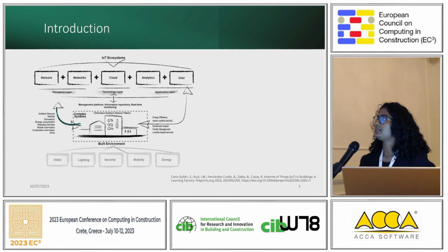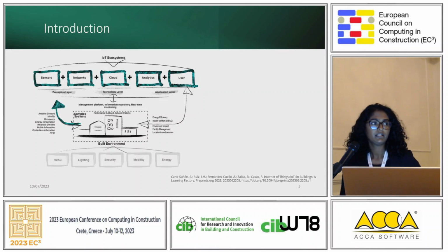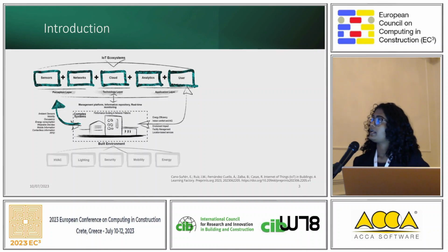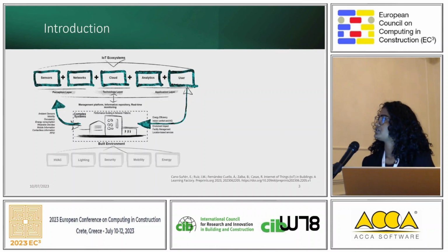So when we say smart buildings, we are talking about a lot of sensors, networks, cloud, analytics, users involved in the smart building. And what's basically going on is we have sensors in the building, so we acquire real-time data from the built environment and then send them through the network to the cloud, do some analytics, and that data is the input to a lot of algorithms to fine-tune the operation of the building, and then those controls are fed back into the building to keep the built environment in optimum conditions.